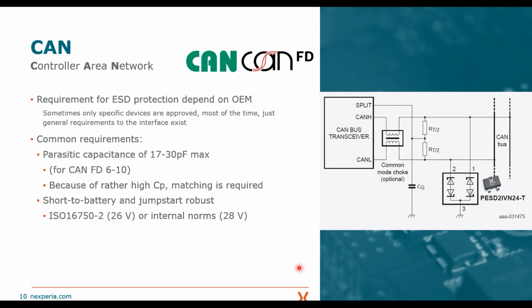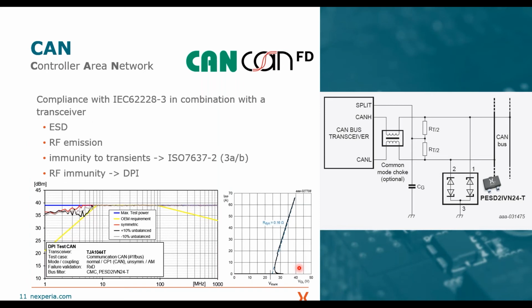And again, other requirements such as short battery and jump start need to be considered also for CAN. For the testing itself, for the ESD protection, there are kind of similar tests required, at least on the first look, and defined in these IEC norms. And you see the tests are kind of similar to LIN, but if you look deeper, there are very significant